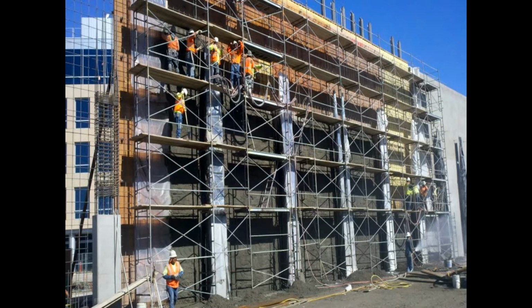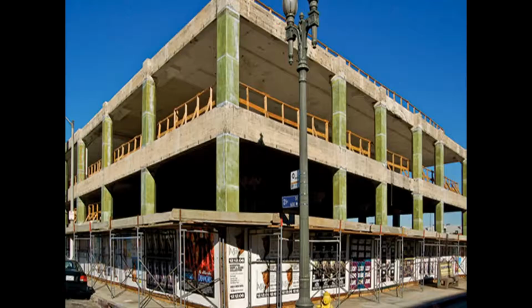In this course, we will learn to understand the basic performance of concrete and steel as structural materials, and the behavior of reinforced concrete members and structures. If we understand the basic concepts of codal provisions for design, we will be able to approach the design in a more knowledgeable fashion and understand the changes in code provisions better and faster. The overall goal is to be able to design reinforced concrete structures that are safe, economical, and efficient.